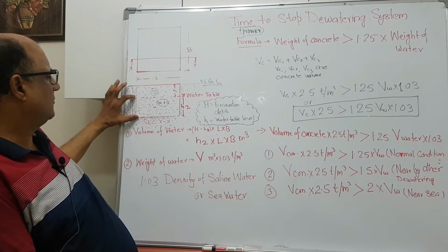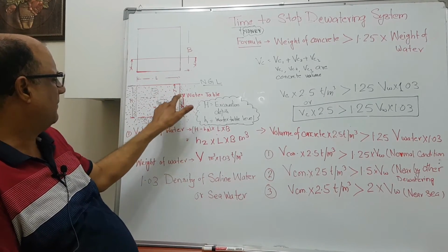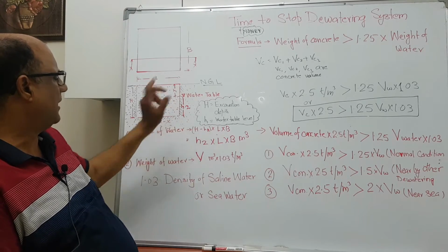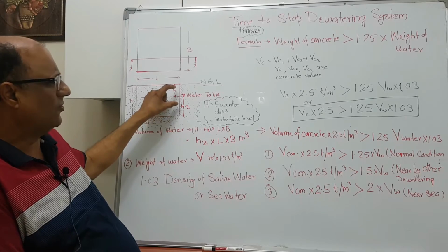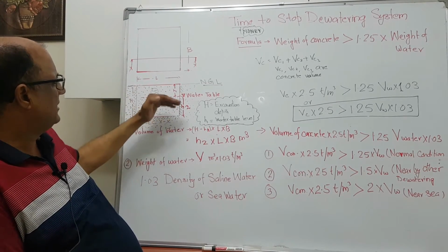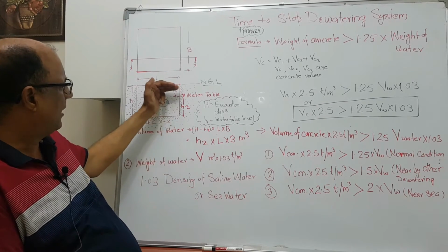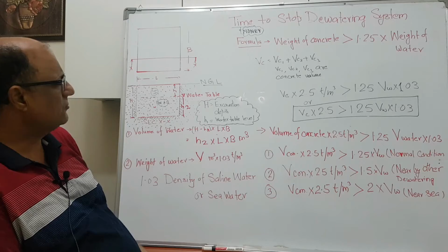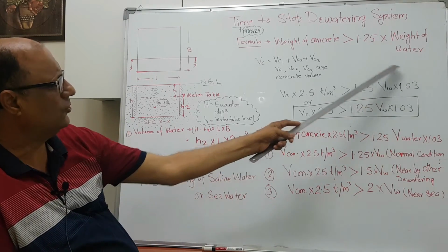See, this water table, during the soil investigation report, was at this level, but it may go down, it may come up, because it is a seasonal factor. This is not under the control of any human factor. So this may go up, this may go down. How much will it go up, how much will it go down? So we should have some factor of safety for the variation in the water volume.